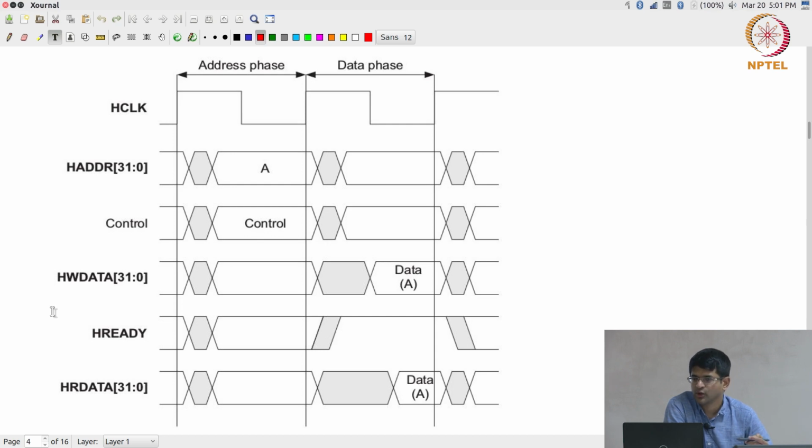From an implementation point of view, we just do it this way because it is easier to visualize things by saying that there are separate write and read buses, even though the high level diagrams that we draw indicate that they are the same bus. In practice they go through some tri-state logic and end up coming out as two separate buses inside the chip.